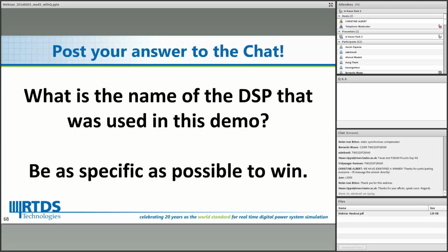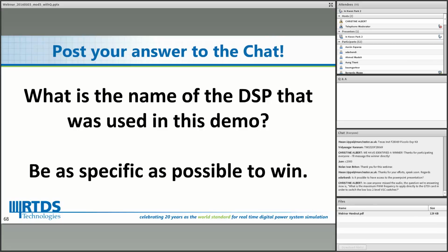Because we are talking about the low-loss bridge model, probably you don't need to be concerned with the artificial or fictitious loss associated with the higher switching frequency, but still the fundamental fact is there. What I mean as a fundamental fact is that the size of a small time step is there. As I explained in the first part of this presentation, the size has to be around probably 1% of your PWM switching period.